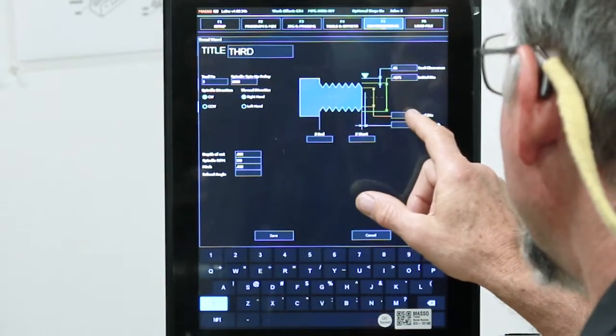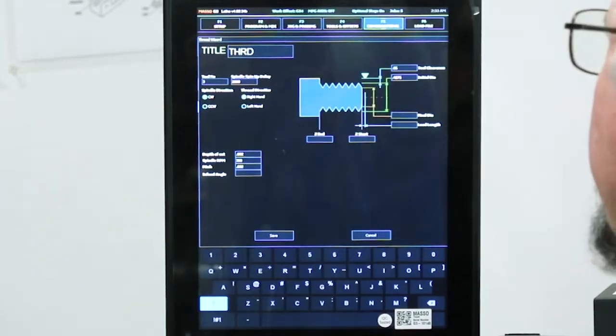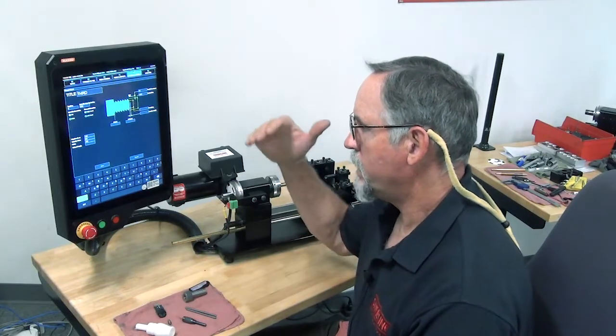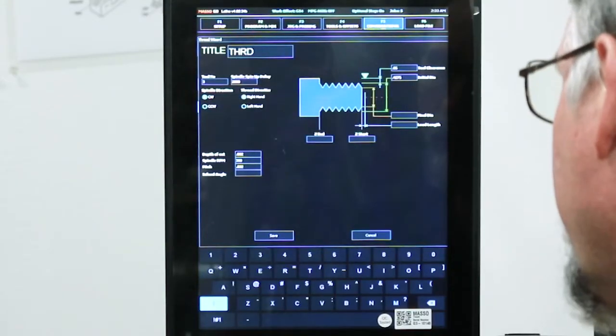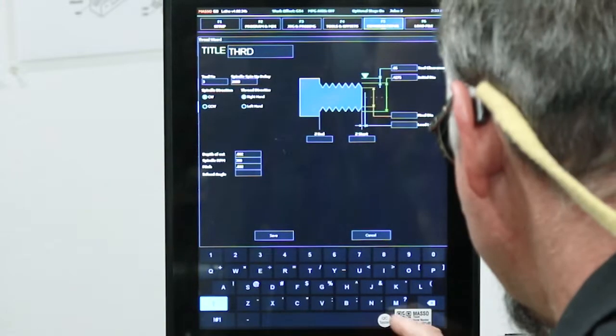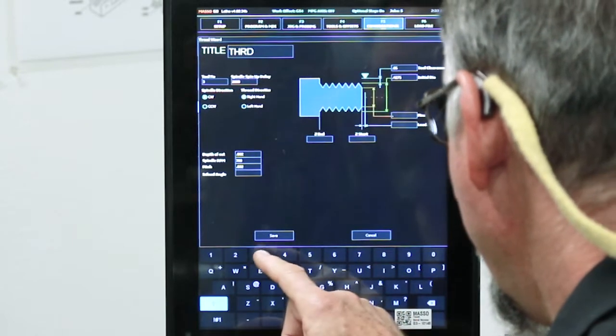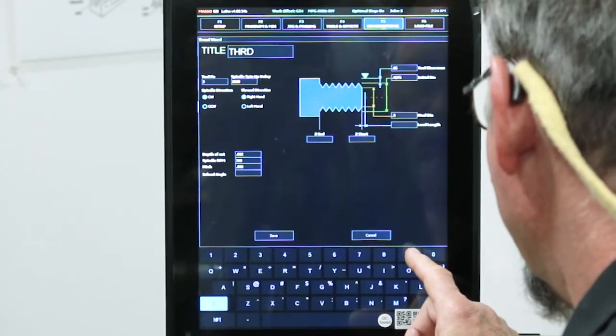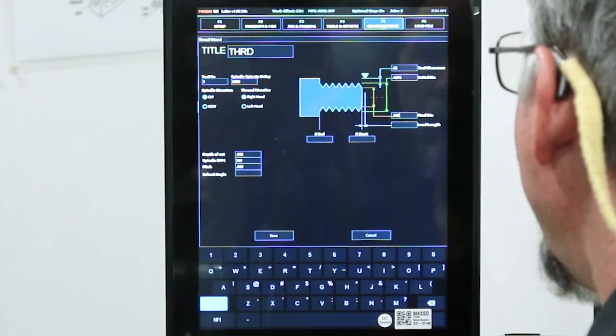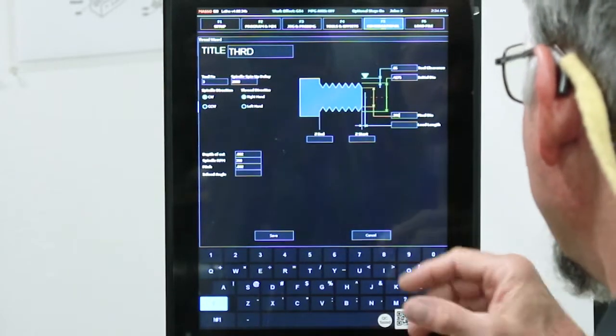My final diameter, 32 pitch thread, is about 15 thousandths thread height, so 30 thousandths smaller than that. So we got 0.3, we'll go 390, we'll make it just a little bit deeper, 390 for my final thread.